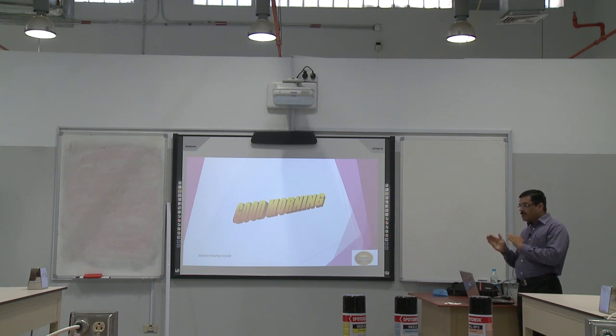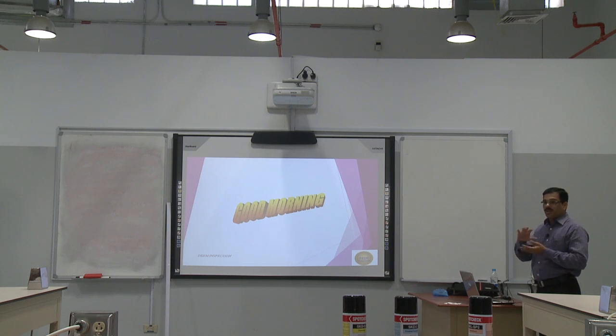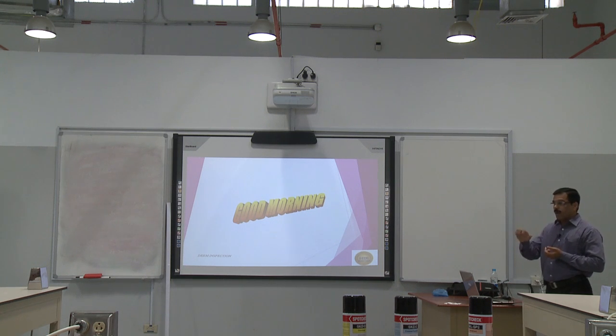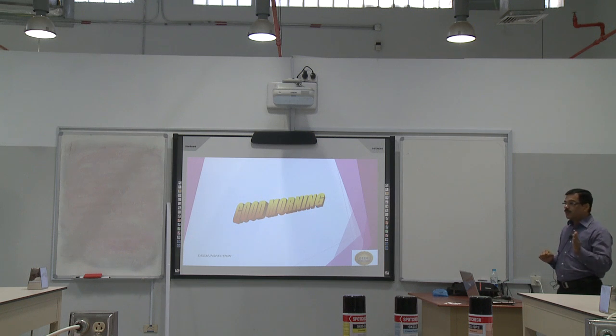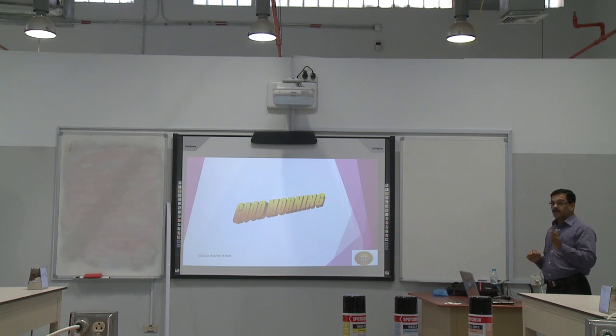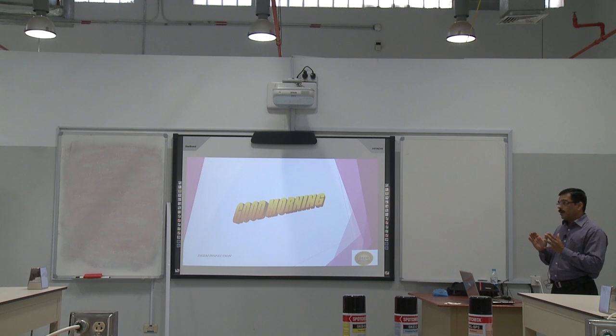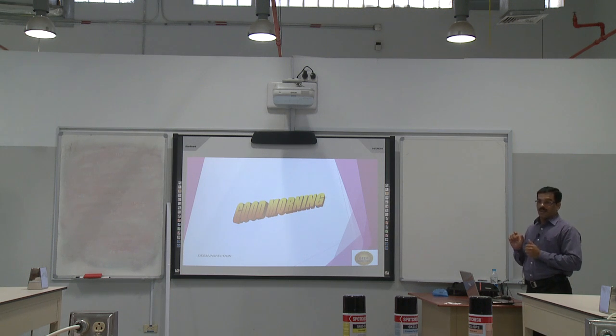To overcome this problem, because in industry we have so many other materials like stainless steel, aluminum, glass, plastic, which we cannot magnetize, another NDT method we are using to find surface discontinuities is penetrant testing, liquid penetrant testing. Liquid penetrant testing is an NDT method we can use on all material except porous material.